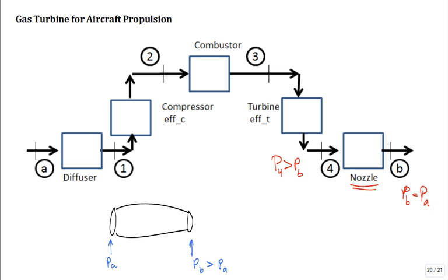But it's not. And you can argue with a lot of people, or they can argue with you, well, how does the thing work? It's got to have a high pressure and push it up. But it's not. So the exhaust gases come straight out like that, or close enough to straight out. And the pressure there is the same. So the key is throwing it out at high speed. V sub B needs to be high, high, high.